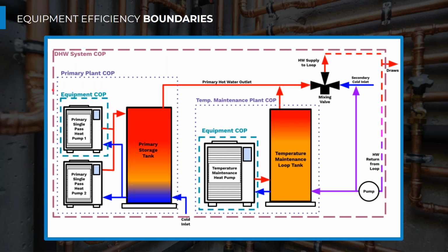That's looking at the domestic hot water system COP, because they understand that we want the highest efficiency systems possible. And so we need to be focused on that rather than just looking at the equipment COP, because even though the manufacturer publishes maybe an equipment COP of 4, we're not going to see that in practice. And the folks creating that Advanced Water Heating Specification are really trying to get a real life efficiency metric, and that's that domestic hot water system COP.